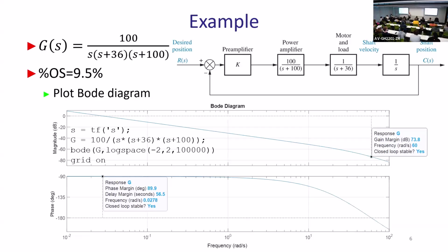Okay, so you have multiple ways to do that. First of all, you can do that from physical laws about how currents work, Kirchhoff's law, and there is a full development in that same textbook, if you go some chapters, of how they develop specific things. But in practice, you typically do not know the physics of the system, so you can estimate the parameters of the system. You assume something first order or second order, typically, because this is the easiest one.